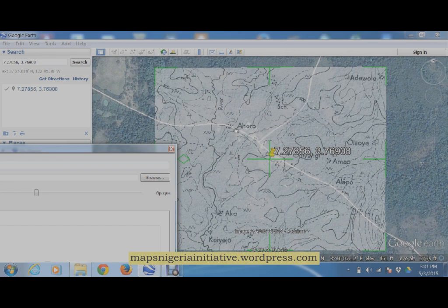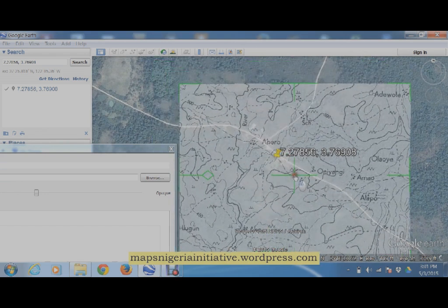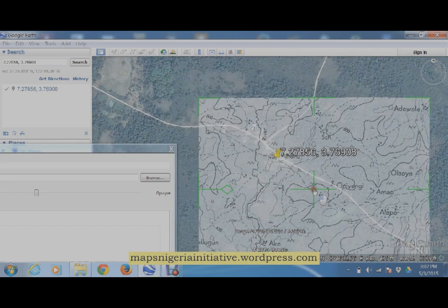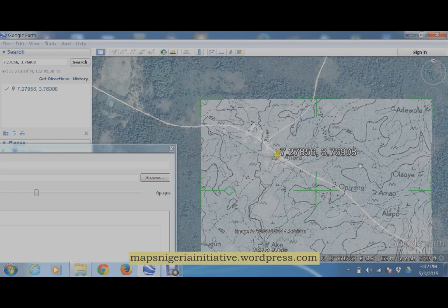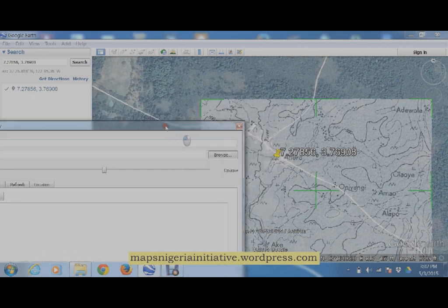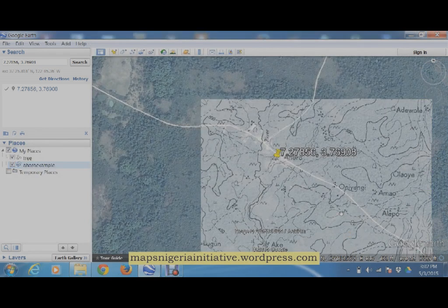I want to bring this arrow to where the pointer is, exactly there. So now we've been able to shape our map properly so that it stays the way it's supposed to be on that GPS coordinate, something like georeferencing, so to say. So we click okay, and now we're good. You must do this for your image and make sure the exact spot is exactly where it's supposed to be.